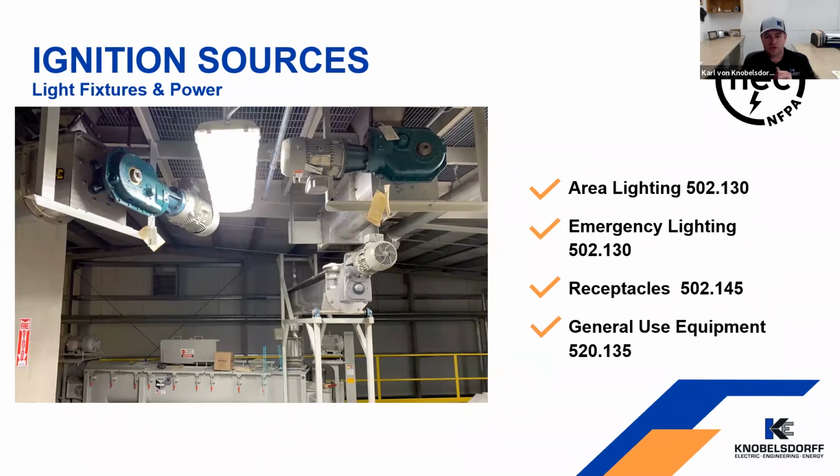So light fixtures and general power, area lighting's covered under 502.130. Emergency lighting's covered in the same. Emergency lighting is something that's often overlooked, where they'll spec out a Class 2 Div 1 rated fixture or a dust ignition proof fixture, but then the emergency lighting is just a standard NEMA 1 type fixture.